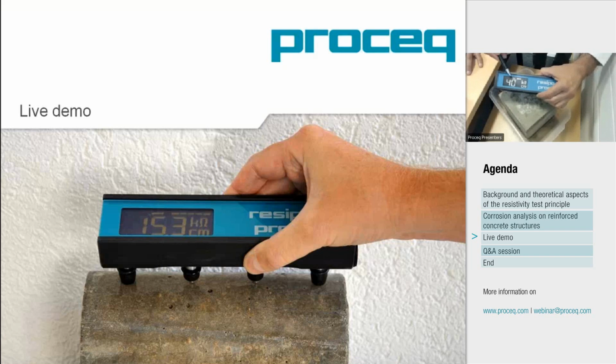For higher resistivity, we can go down to 50 microampere, and then we have an indication of the percentage of the scale of the electrical current that passes. So the measurement in itself is very simple, rather quick, and especially since we are actually out on site, maybe close to the sea, close to the water, we need an instrument really ready for harsh environment.